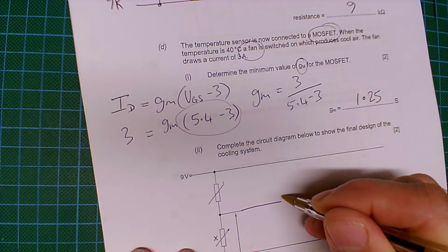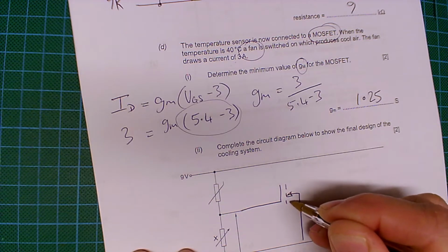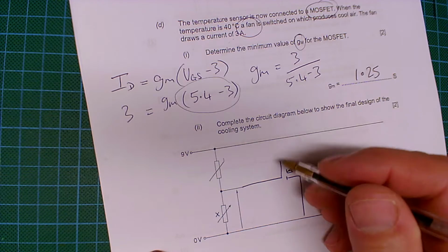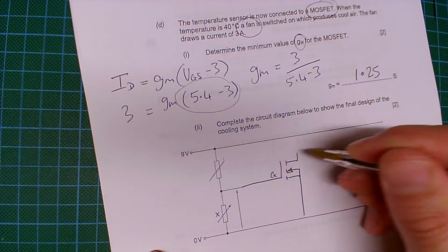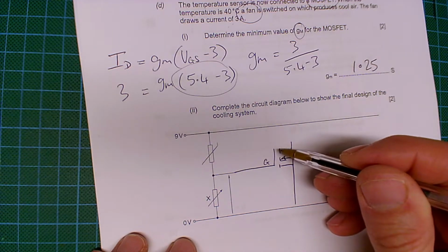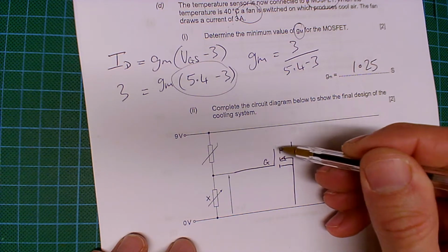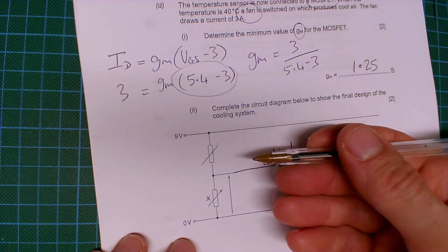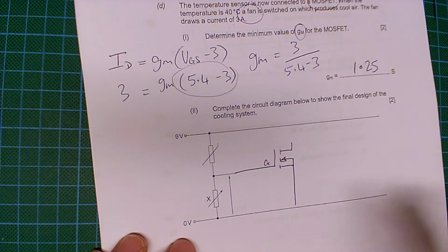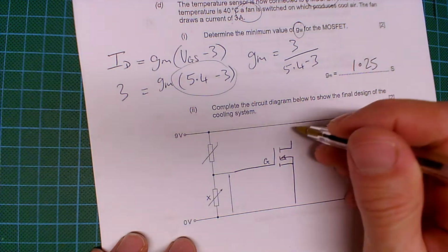So let's just draw the MOSFET. Now a MOSFET has a very high input impedance. Think of impedance as resistance into the gate. That's the gate. Notice where I drew it. It's like an L there, and then we've got 3 lines, and then the middle one has an arrow facing in, and then we've got these lines like this. It's important that the arrow faces in. That's the particular type of MOSFET that you'll learn about at GCSE level. Don't worry about any others. But you do need to draw the arrow in. It needs to be the correct symbol, okay?